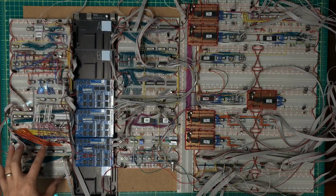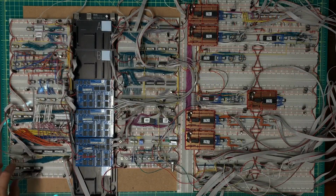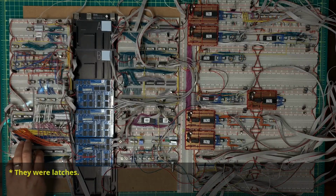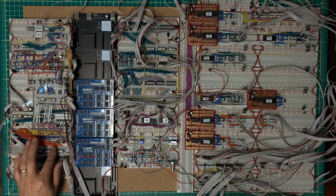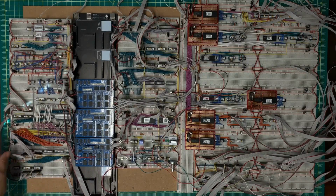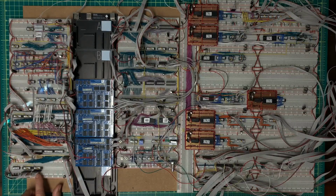Okay, the first order of business is down here in the corner. I need to undo the changes I made, so I no longer need the line drivers here. I no longer need the latches here. These orange connections can come back down here to where they were originally and be wrapped around the bus lines here that are ribbon cables. And then I want to swap out these pull down resistors for 10K ohm resistors. Get that process started as well. So let me jump in on that and get a lot of that work done quickly so we can get it out of the way and then start focusing on signals.